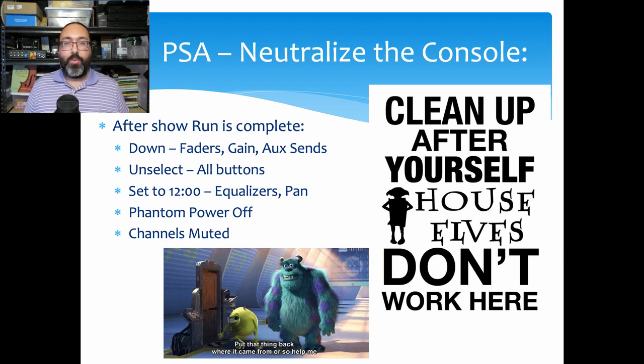The other thing that you want to do, and I know a lot of engineers don't always do this, is make sure that your channels are either muted, or if it's one of those consoles that have an on off button, make sure you check to make sure all those channels are off. Now, as I said, not as big of a deal with digital consoles because you can factory reset them. A lot of times, guys are coming in with their own show file. I will always come in with my fresh show file because I don't trust what anybody else has done before me. And it just solves so many problems when I just come in with a fresh show file. But it's still important, especially your first couple times that you come in with it.